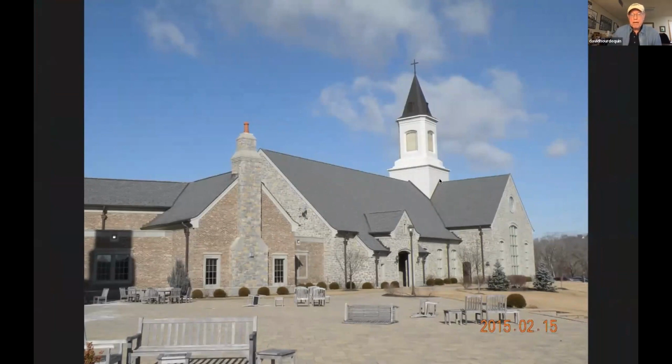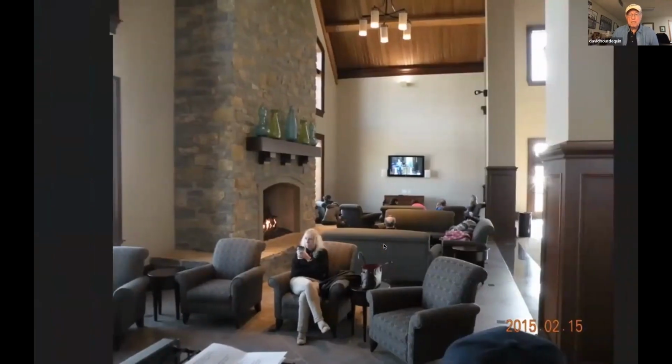And I can't remember exactly how that was framed, but there was a piece running up the rake and down the other side. So I guess for all practical purposes, this part of the truss was loaded with that vertical load, that trapezoidal load going across that face and going across this face. And all of these loads just work themselves down into each of the four faces. But it was a challenging little design.